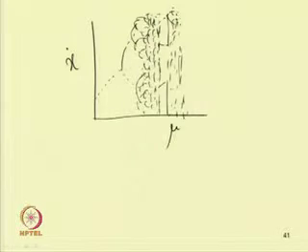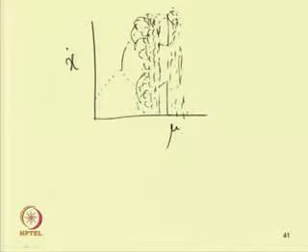While taking this Poincare section, it is important to know how to sample the time response. For example, in case of periodic response, one should know the minimum time period of the system. One can find the minimum time period by studying the resulting time response of the system.